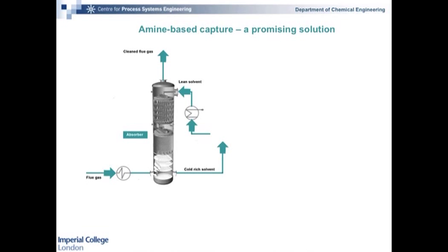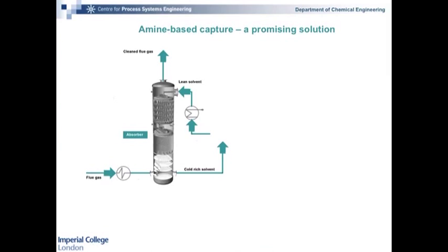So we're going to do something quite similar to what I've just described, except that now the flue gas contains very little CO2, and it is at 1 atmosphere. Okay, so we haven't got pressure working for us. And so what we're going to have to do is to use a solvent which reacts with the CO2 in order to absorb it at ambient pressure. And so, although that works well, it makes the recovery of the solvent much more challenging.